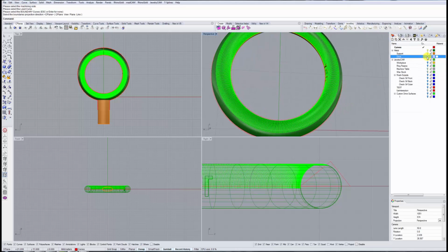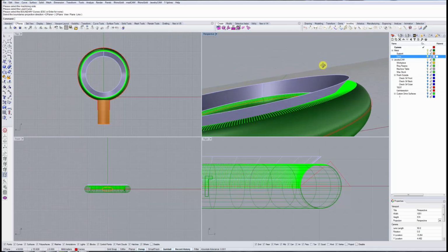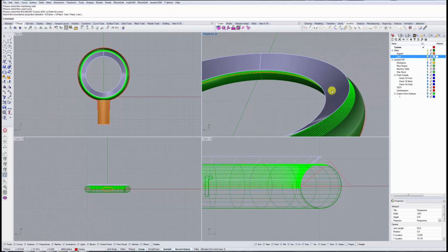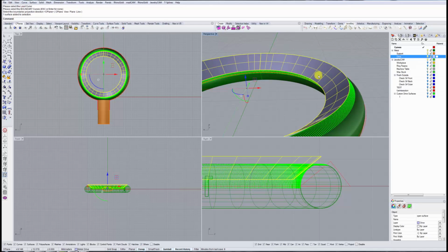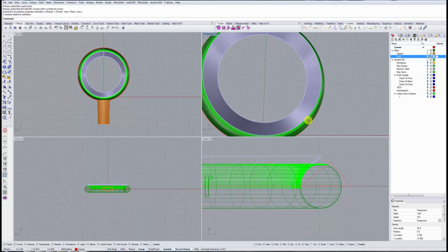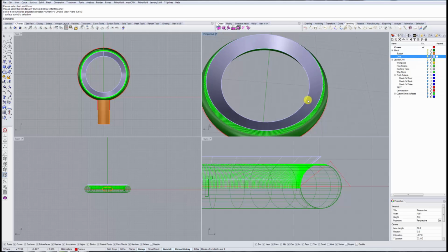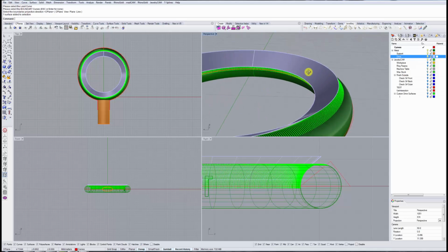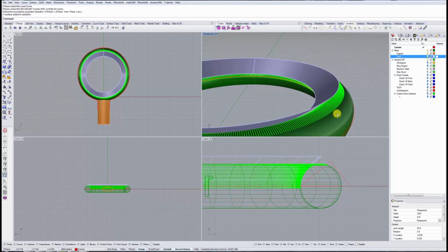As you may have noticed, it's best to keep these drive surfaces in a fairly simple way. This is a singular surface, it's not a polysurface, and it's composed of a sweep without too many kinks or curves. You will get the best quality of cut this way because the mill has to do relatively fewer moves for every single line, and it will already be adjusting the B and the A axes.